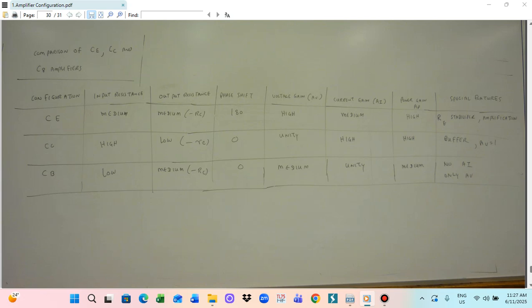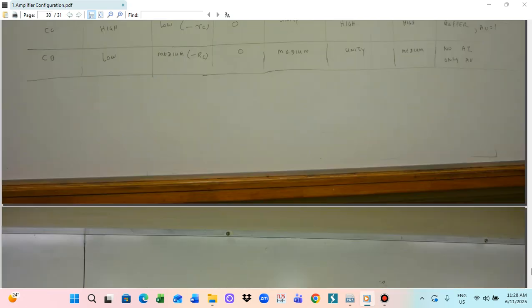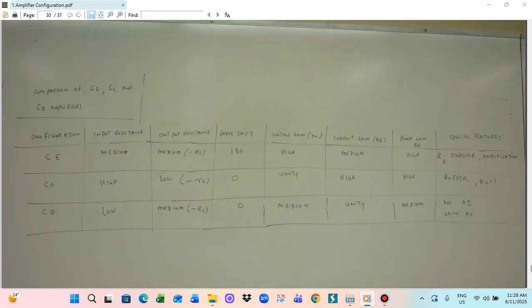Okay, so for this G12 analog portion, today I taught you the amplifier biasing circuit and amplifier configuration: the principle of the amplification and amplifier characteristic configuration. The transistor biasing circuit determines the DC characteristic, and the amplifier configuration determines the AC characteristic. There are three configurations of the amplifier: CE, CC, and CB. Those are the basic principles of the amplifier.